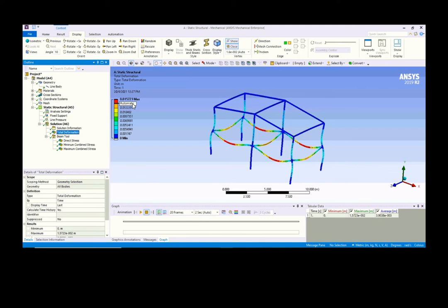Later on, we'll see how to get a suitable mesh size. What we call a mesh independence test is where you play around with different mesh sizes until the mesh size doesn't really affect your results anymore. That mesh size is then a suitable mesh size that you can use for the remainder of this particular problem.